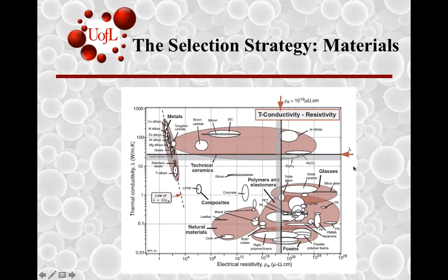Then if in addition you maintain a minimum thermal conductivity, let's say about 25 watt per meter Kelvin based on this horizontal line, then only two options are thrown up over here. These include aluminum nitride and alumina, with the silicon nitride being a close possibility lying just on the line based on this quadrant over here. Everything else is discarded through the process.